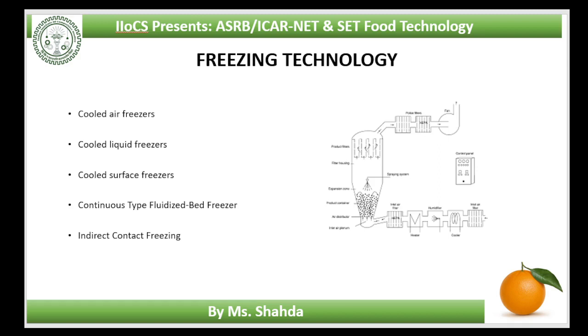Food comes into greater contact with the air than in blast freezers, and all surfaces are frozen continuously, simultaneously and uniformly. This produces a higher heat transfer coefficient, shorter freezing times, a higher production rate and less dehydration of unpackaged foods than blast freezing does. The equipment therefore needs less frequent defrosting.